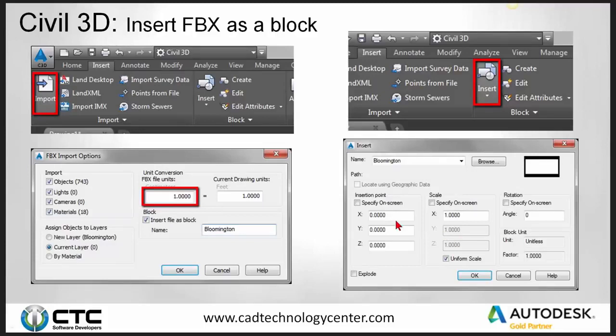So this is where for my X I would plug in the 540,000, and then the Y I'd plug in the 124,000. And if I really wanted to, I could get my Z value really close, and knowing that that area is around 825 for the contours, I could drop my FBX down to an 820, and then I could just slowly move it up a little bit. Again, this is preliminary conceptual. I use it for vehicle tracking, but it's close enough for what I want.